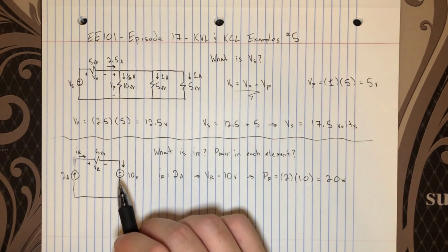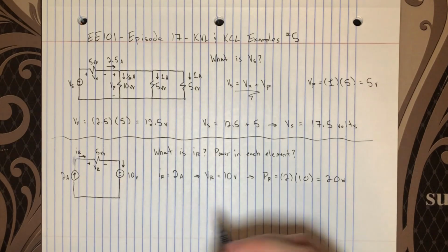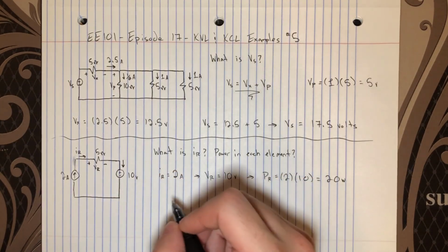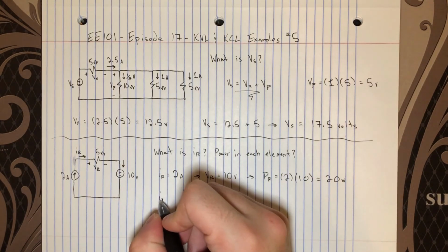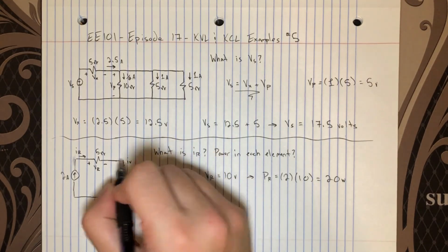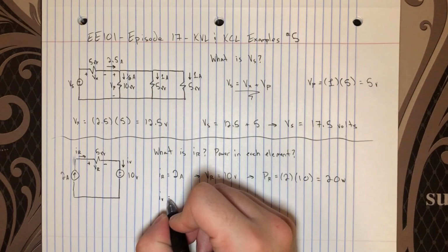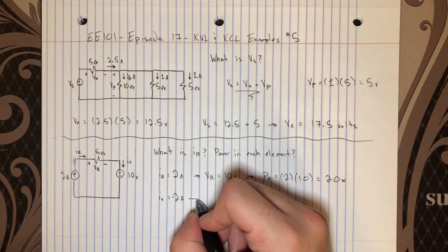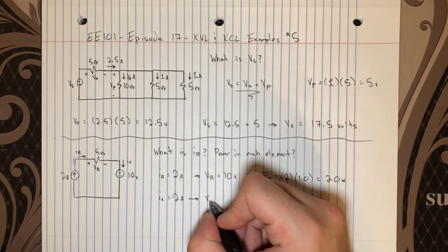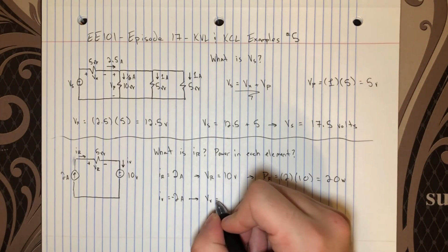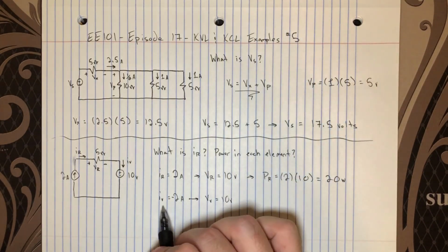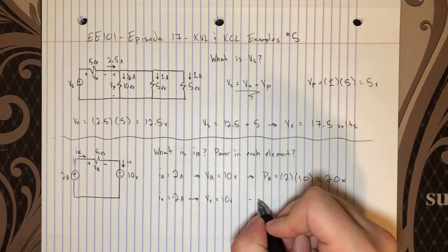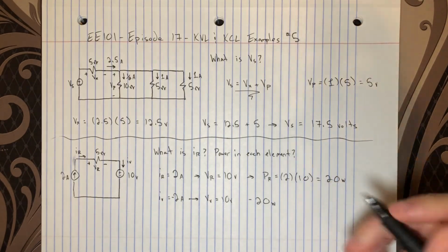And we know how much power by virtue of the fact that we know the current and the voltage here. So I'm going to say the current into the voltage source, let me say IV, which is just equal to IR, is 2 amps, and then it's times the V of the voltage source, which equals 10 volts, as we know. So the current in the voltage source times the voltage of the voltage source will now give us minus 20 watts. That's a total typo.